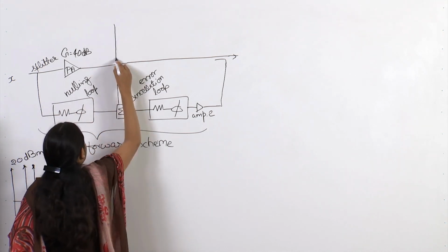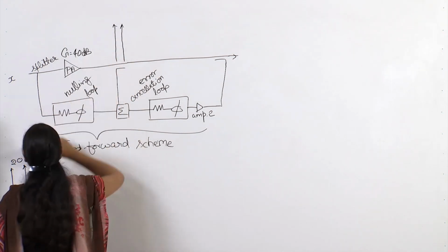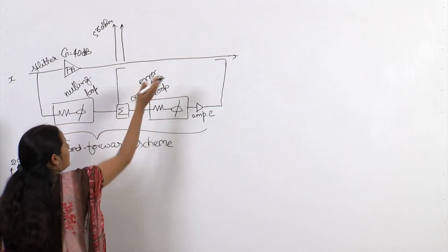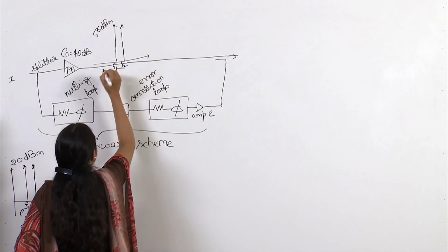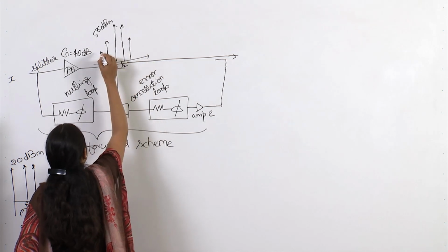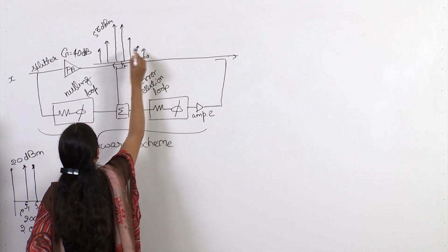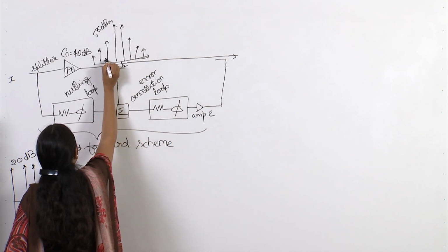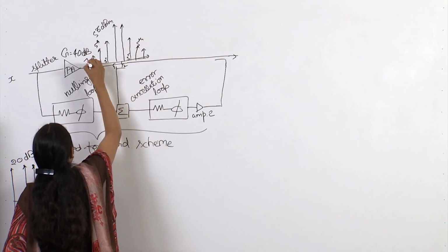But actually you will not see exactly 60 dBm, but somewhere around that, let us say 56 dBm, because some of the power goes into IMD products. So, you have your F1, F2 values, and then you will have your IMD terms: third order IMD, fifth order IMD, seventh order IMD, and so on, and then you will have harmonics. So, it is third order, fifth order, and seventh order.